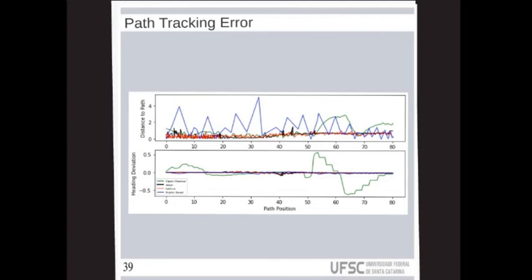It shows how feasible the trajectory was for the control algorithm, and we have the distance to the path in XY here. We can see that the public road, that is the Apollo Auto planner, has the biggest deviation. I believe it's because it developed a bigger velocity while it was running. This bigger velocity makes it harder to track each waypoint, so this is why I believe it has the higher deviation.